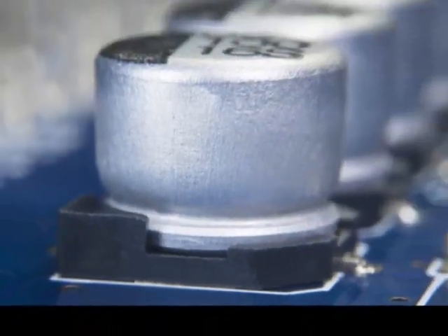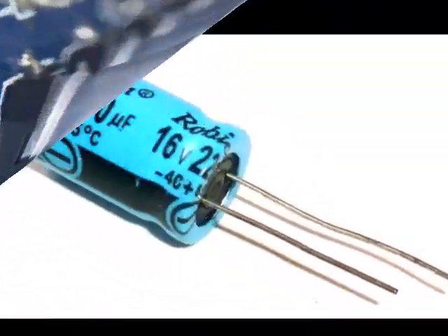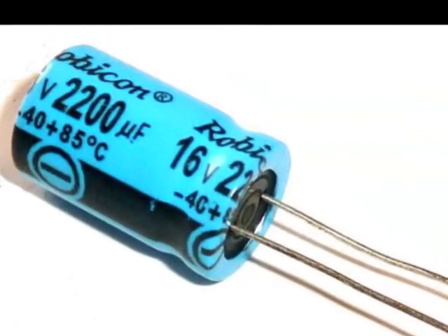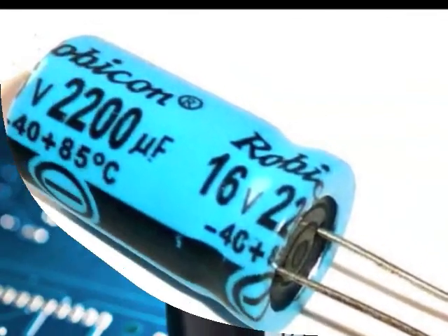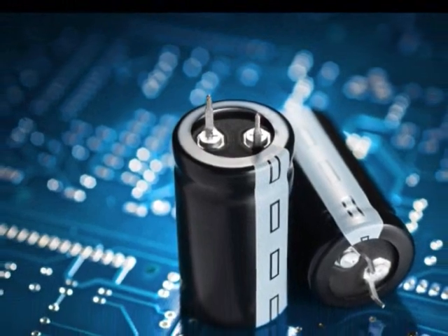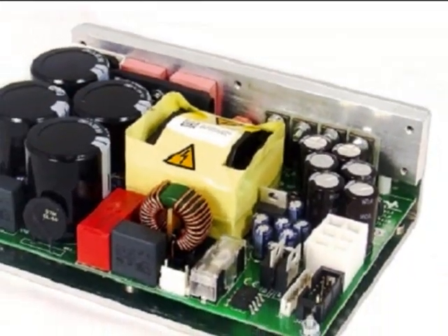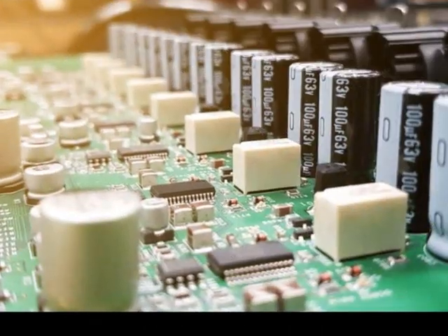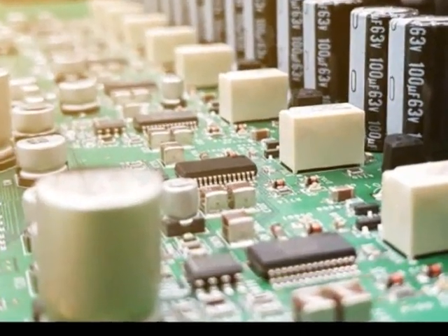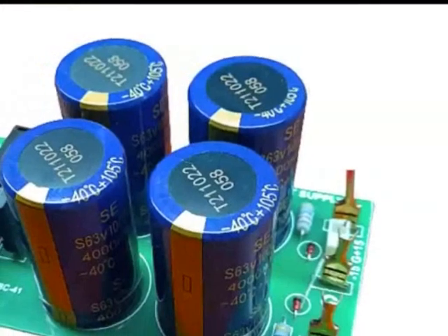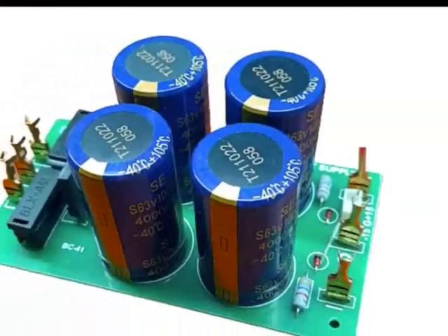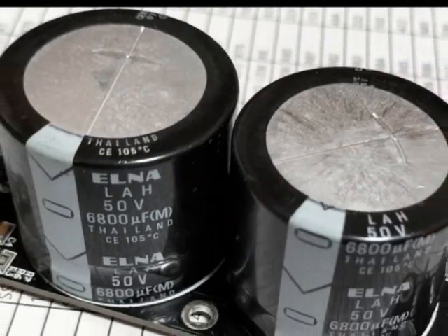On the body of this type of capacitor, the maximum voltage that can be tolerated by the dielectric is entered, and they have two positive and negative bases. The negative pole of the electrolytic capacitor is marked with a white or black strip. This type of capacitor is used to smooth, remove low-frequency noises, and remove voltage waves in the power supply part of circuits.